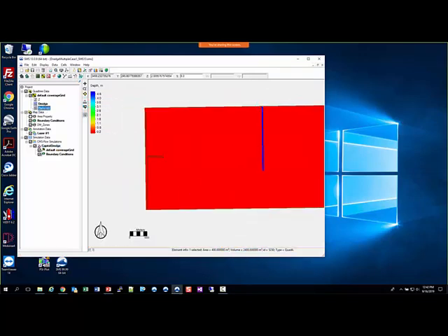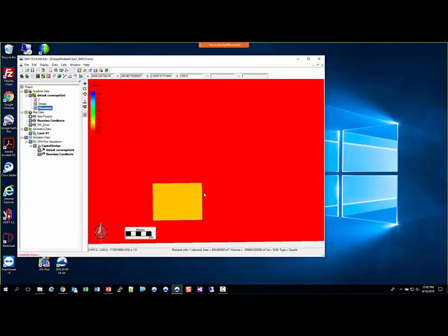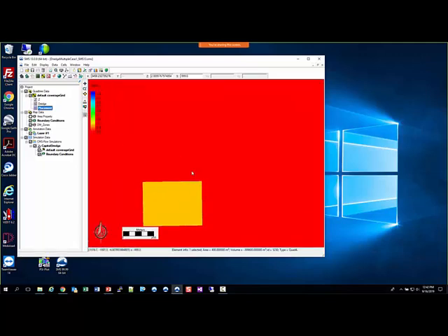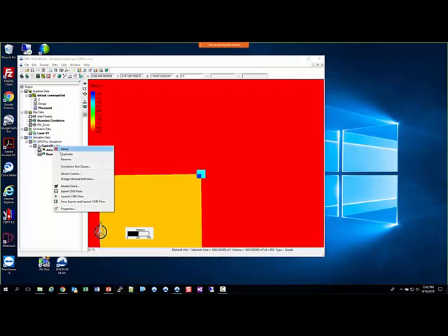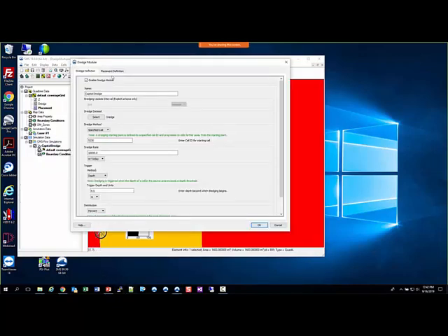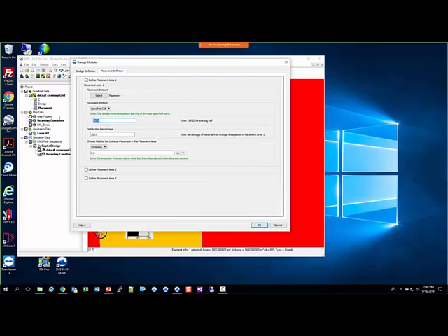So we go over here to our placement area, and we will select this corner cell, and that number is 895 as it shows down on the bottom line. Go back into our dredge module definition, and make this 895. There's only one area that we are defining right now, so we make our distribution percentage 100%, and then our thickness is 1.1 meter thick.